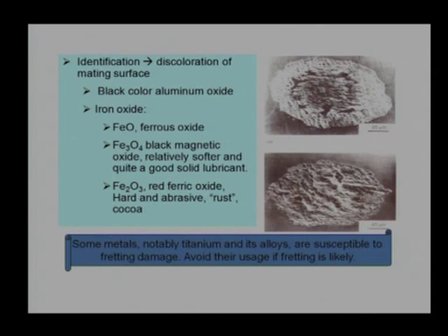There is bone cement which restricts the motion of the implant, but if there is some micro crack in it, or a motion that gives some micro slip initially and then gross slip, that will cause damage to the implant. So that is also related to fretting wear, which can be studied in detail if we go to the micron scale or nano scale.